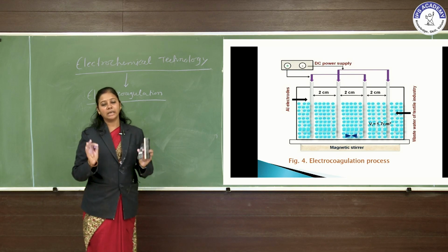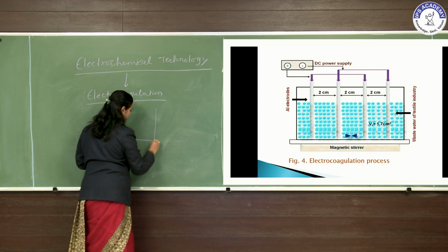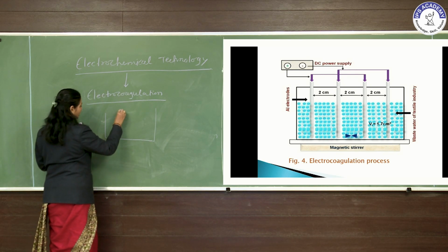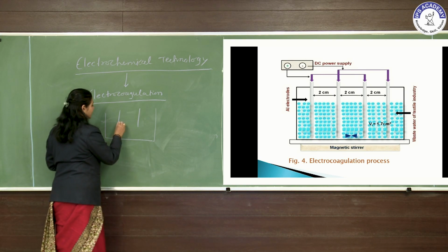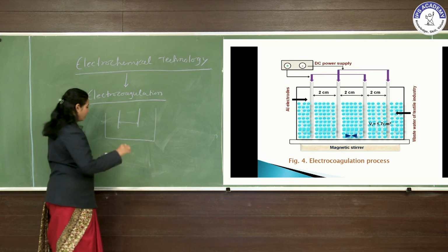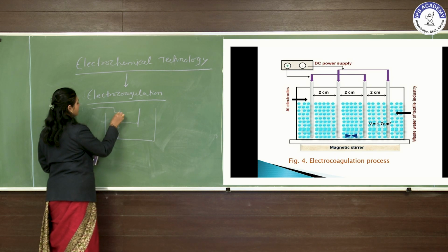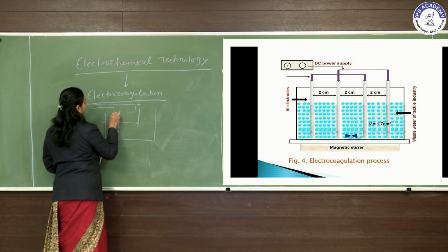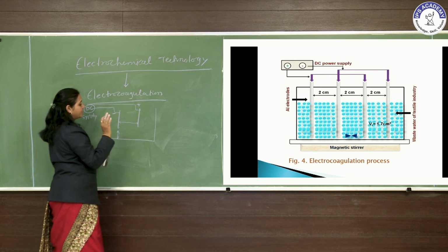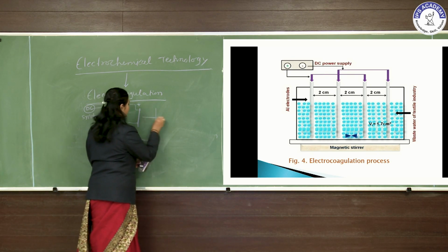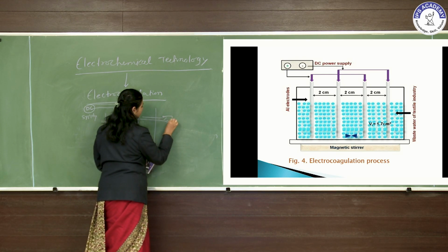Electrocoagulation is nothing but the electrolysis of the wastewater. Okay, you already studied this electrolysis. There are electrodes placed in a reactor with a specific distance in between them, with a specific distance from the bottom, and these are connected to the DC supply. So this is the very basic diagram I am drawing. One is called cathode. These are the electrodes. One is cathode and one is anode.